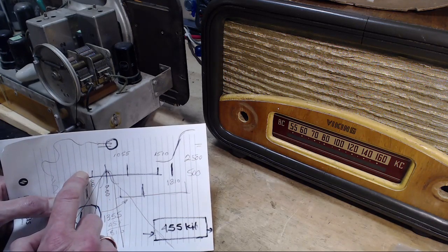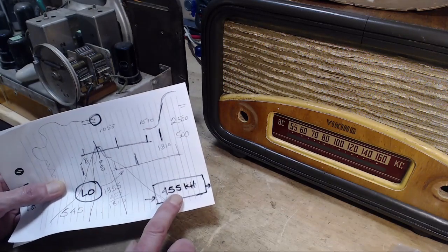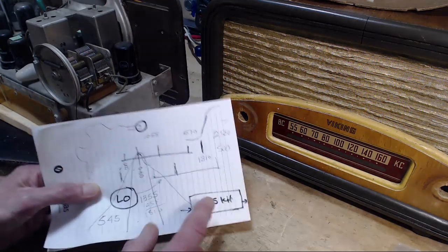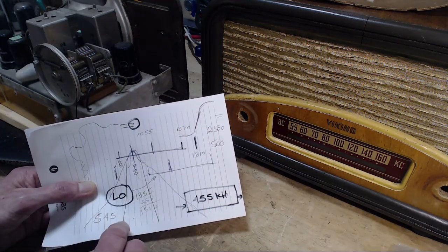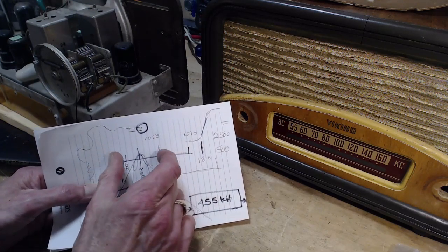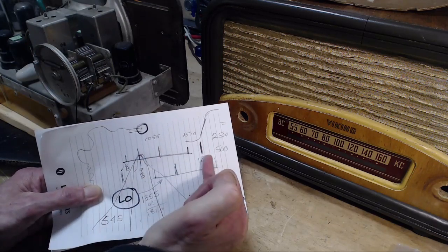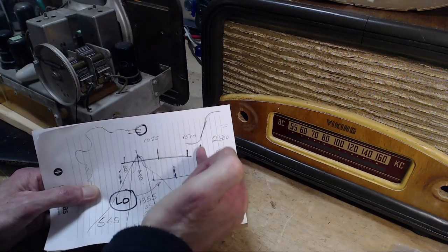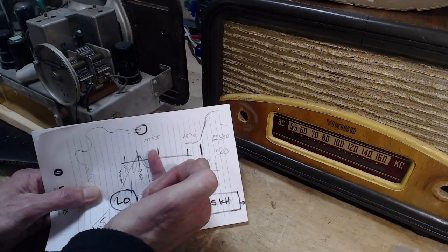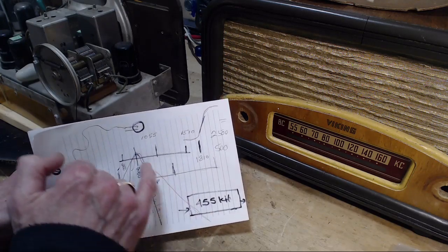Now if we're looking at a shortwave radio, this one's not a shortwave radio, it's still using 455 kilohertz. The problem is, you could think of it this way. These curves, you could think of as remaining the same while the band gets crunched down, down, down. And that's bringing this potential interfering signal closer and closer, or further up under this, whichever one you want to think about.